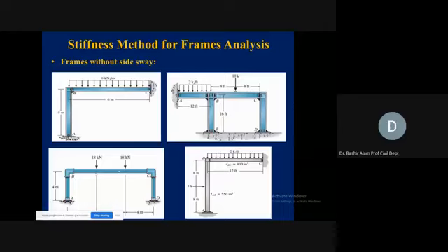Now the horizontal member, if we look at 4 meter, we have from the ends this 18 kilonewton. So we have the member symmetry, we have the support symmetry, and we have the loading symmetry also. It is a symmetrical frame as a whole. Because of this symmetrical configuration of the loading as well as geometry, it is not allowing any sideway movement. So again, it is an example of a non-sway frame.